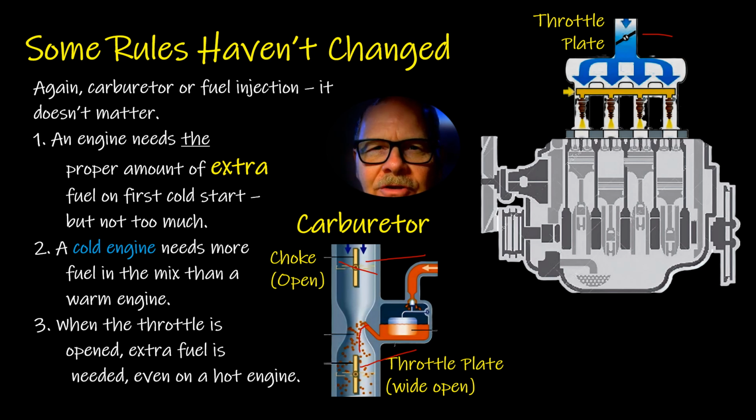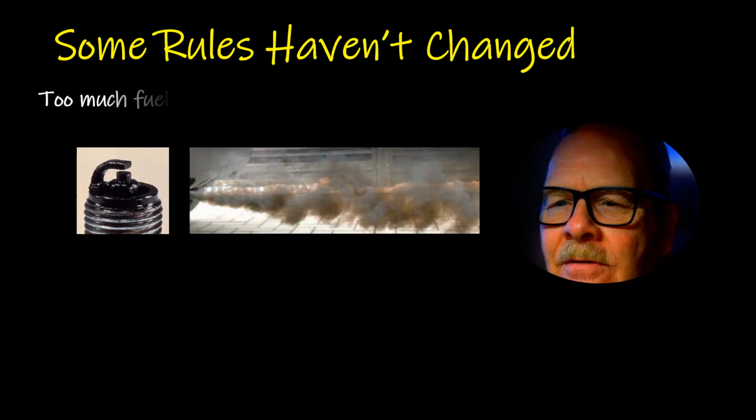The engineers knew that, and that's what that dash pot thing I was talking about two or three weeks ago is. It's the same thing. The dash pot on the carburetor does the same job as the idle air control, holding the idle speed up and then letting it go down slowly when you let off. The engine needs the same thing. It just does. That's all there is to it.